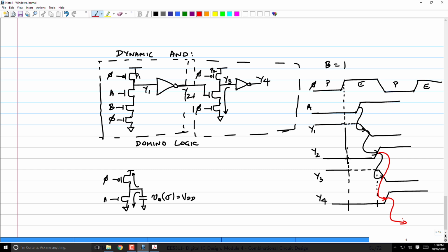Okay, any questions here? True. See, therefore, the moment I start making a circuit, there is a spec that has to be met. It's not how many you have to put. You have to size these so that they meet a timing constraint.